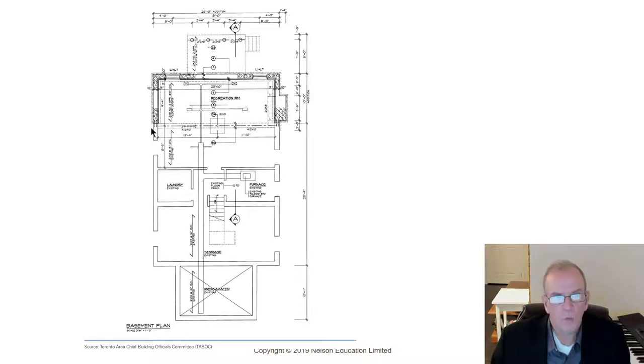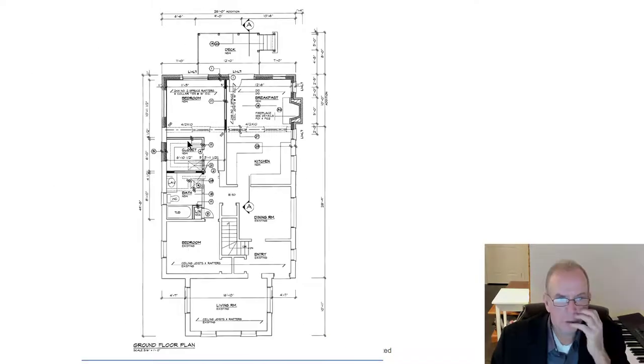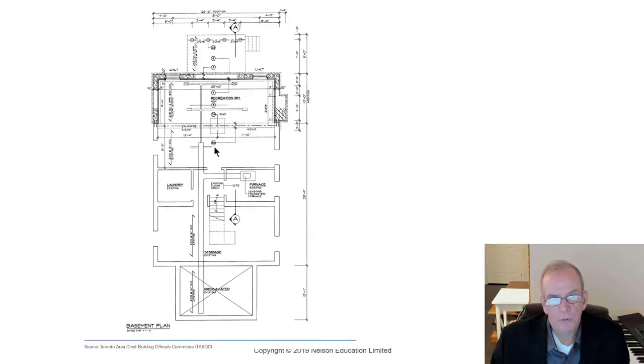You would take out this wall. You would put in the wood beam, and now that's supporting the floor. So at that point, then you could proceed how you would like. You could then remove the back portion of the wall. Myself, I would probably have the footings going around. I would probably have the back of the house, the foundation wall put in, and then I'm starting to look at this portion here, because once I've got that supported, I can take this out and I can build this floor in and tie everything to it, and then I can go up from there. So you're trying to think strategically how you would go about this in the best way possible.